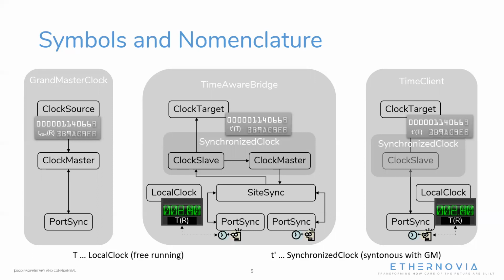You can see that all of my time-aware nodes in here show this synchronized clock. Keep in mind that this is not necessarily a requirement for a bridge. If you have a transparent bridge, then this synchronized clock in the bridge is actually not required, but we will see that if you follow the proposed solution that I'm presenting here, then you will need a synchronized clock within the bridge.